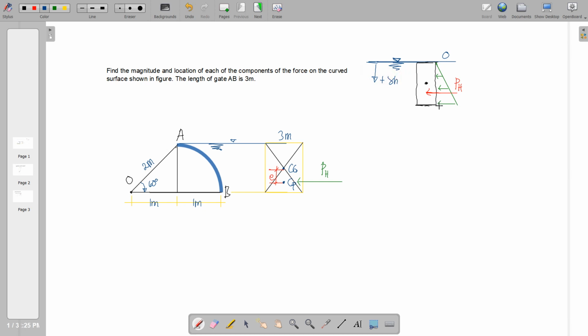So therefore, this pressure distribution starts from 0 up to an increasing value. So that is why that is in triangular form. So this pressure distribution is fully distributed to the submerged portion here, because there is no space for any void to distribute this triangular shape pressure. So therefore, this is gamma h.